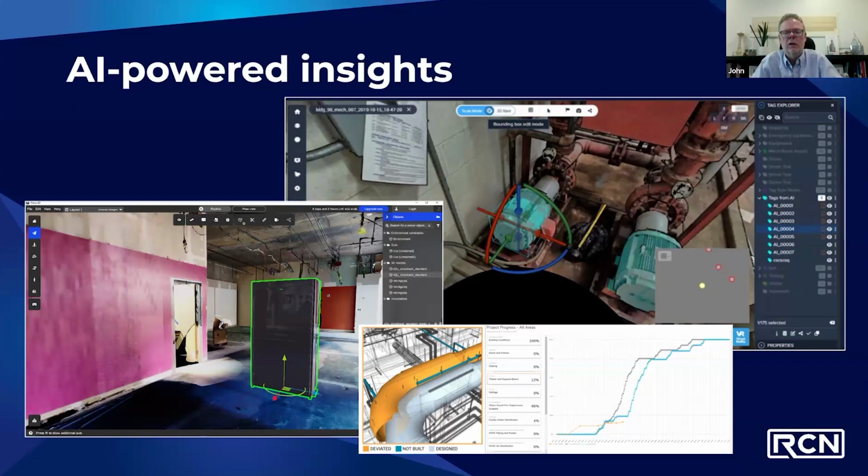In cases where you have structural steel, but there's no provision for supplemental steel to be modeled, you have a real problem, because that supplemental steel is going to be in the way of certain things that are going to be in that building as far as finishes and mechanical and electrical. But absent of that, you're not going to get a clash because it's not there, right? And so that data that doesn't exist has got to be made up, or it's always going to be missing, right?